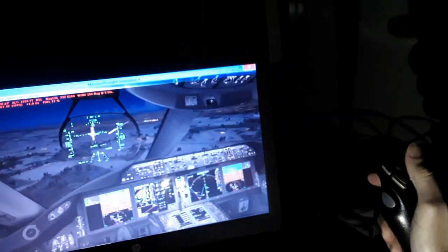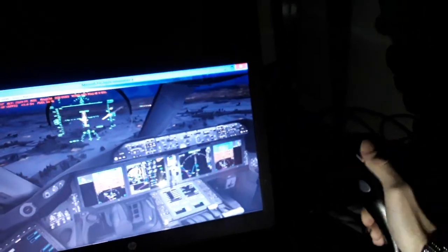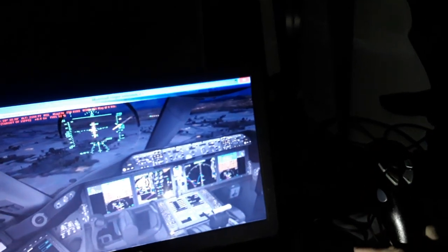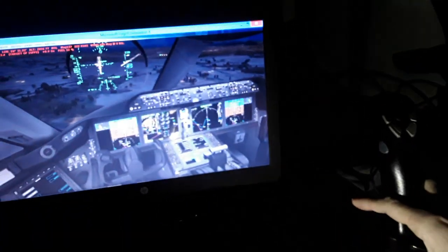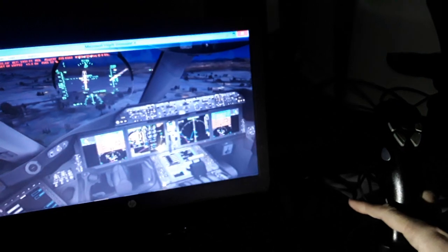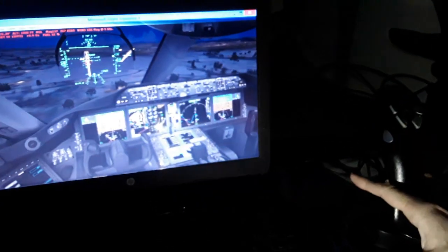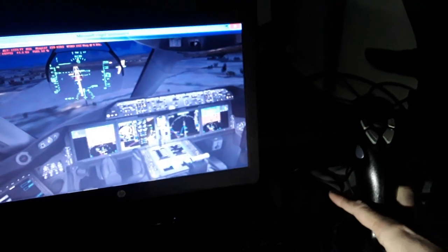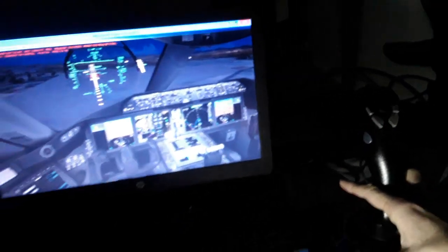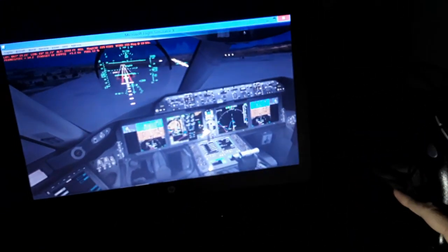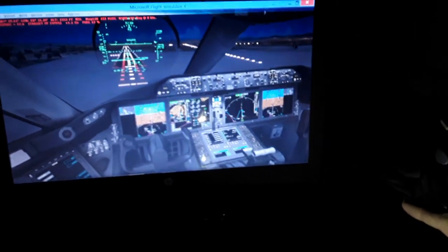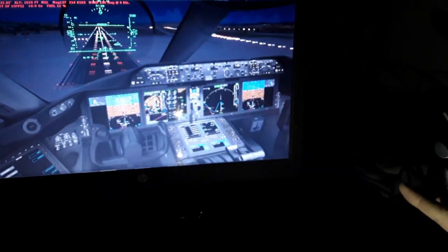So we have some side wind, we need to balance the aircraft using the flight controls, a little bit more thrust up, and we have a few more seconds for the touchdown, align with the runway heading. Over here we're going to make a very nice landing, idle thrust.